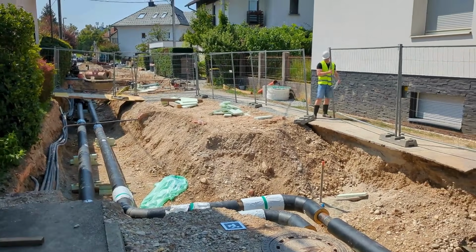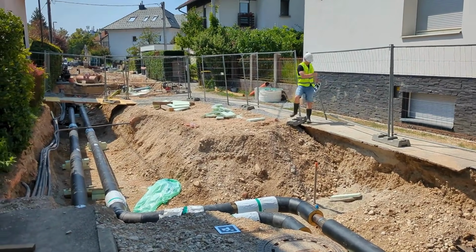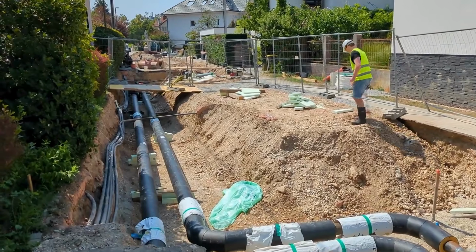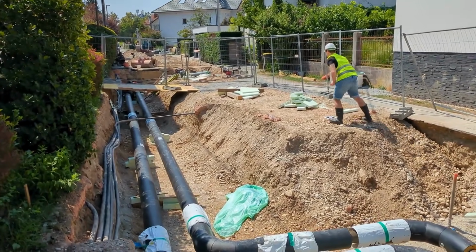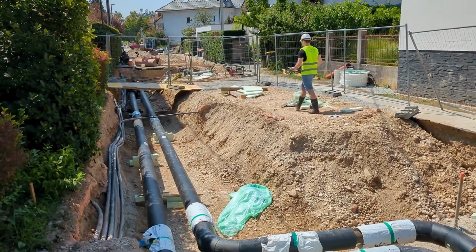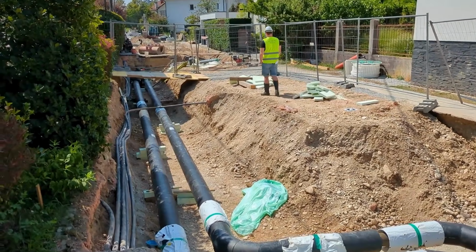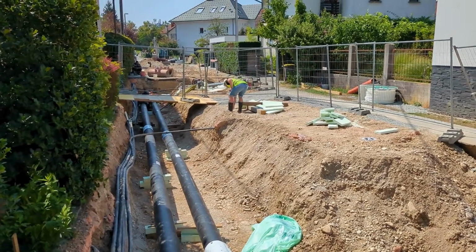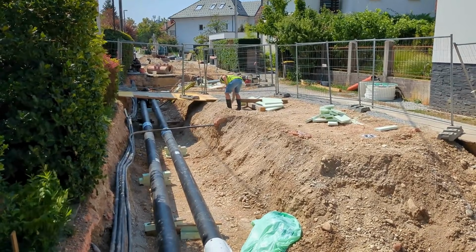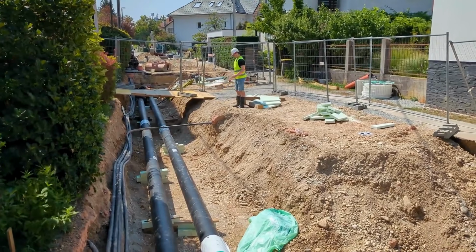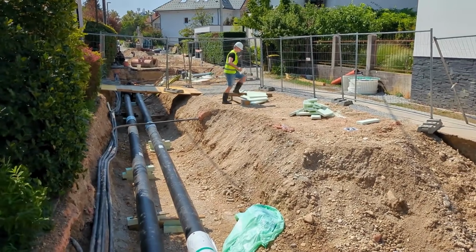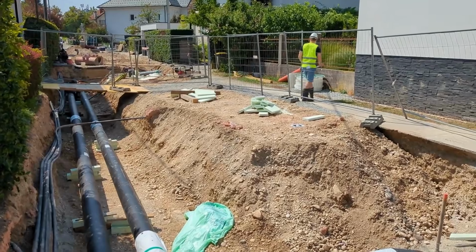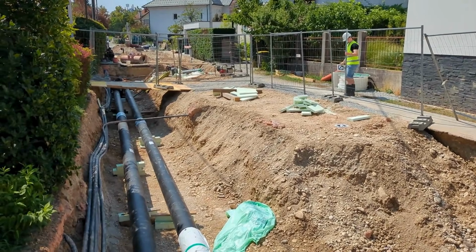Everything that's inside the ground control points should be super accurate. From our experience, if we do the measurement without ground control points, so just with the video recording in the 3Dsurvey SiteScan app, we can achieve accuracy of 10 centimeters, something like that. If we additionally measure ground control points, we can go to centimeter accuracy with the orientation.